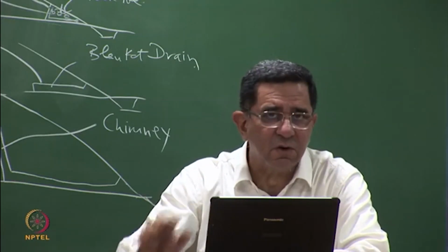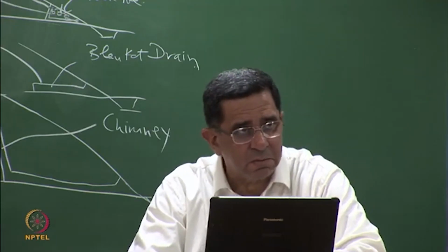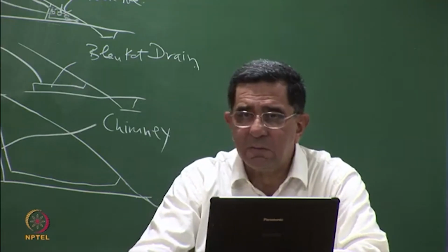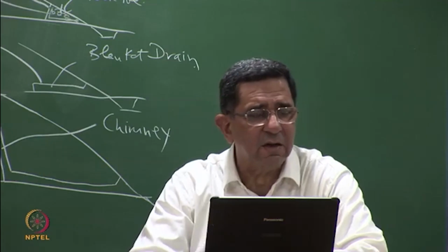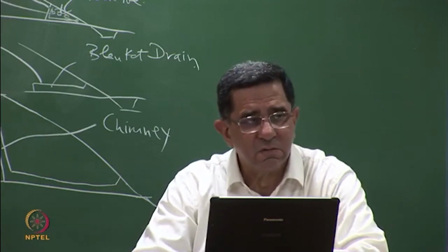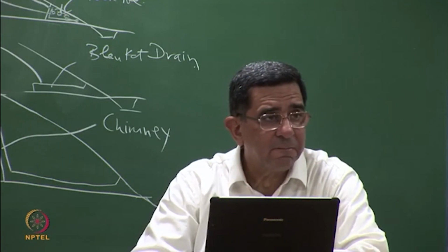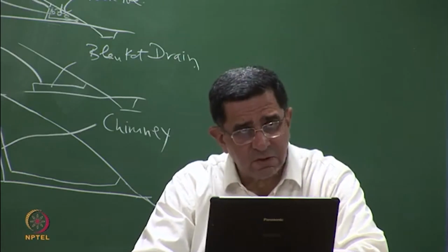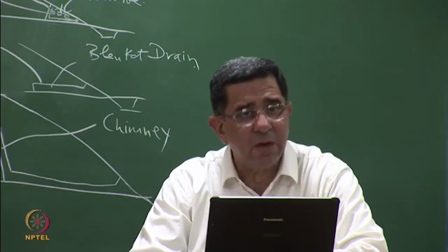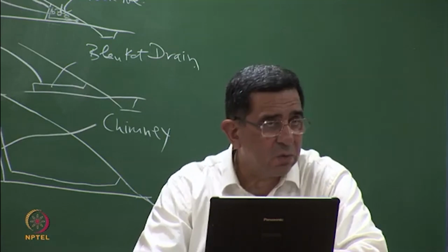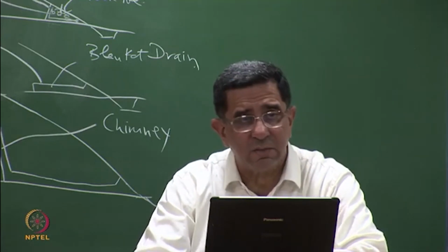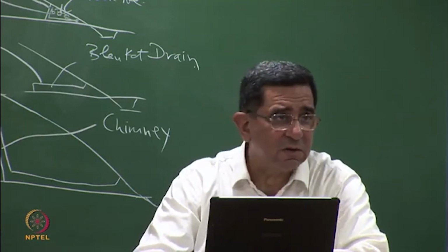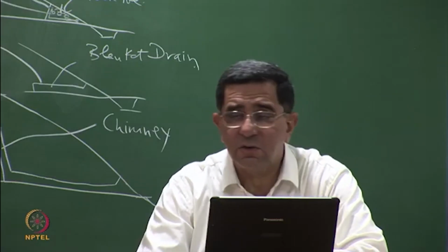That means the factor of safety of your embankment should be above minimum acceptable. And you remember what's the minimum acceptable factor of safety for a static case without earthquakes? 1.5 is the normal acceptable factor of safety. We must have that. And with earthquake, if you are using the pseudostatic method, the factor of safety acceptable is lower. How much?